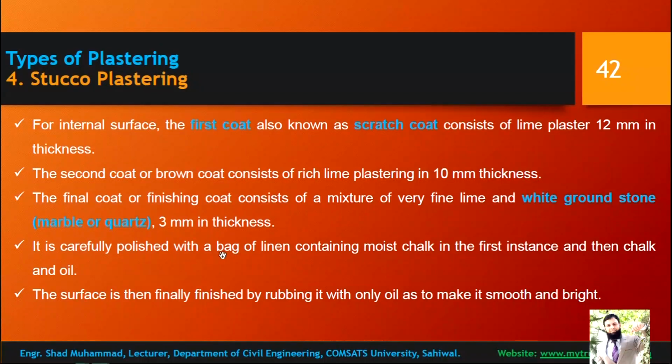It is carefully polished with a bag of linen containing moist chalk in the first instant, and then chalk and oil. The surface is then finally finished by rubbing it with the oil to make it more smooth and bright.